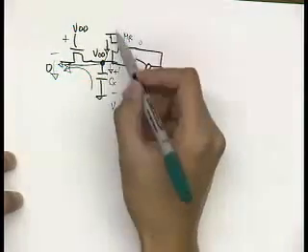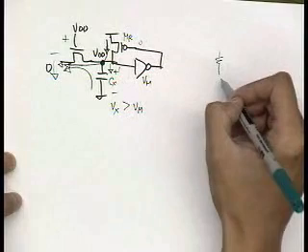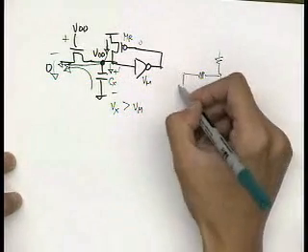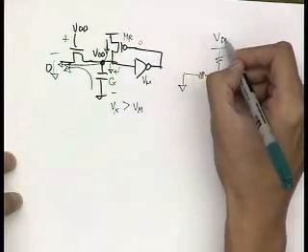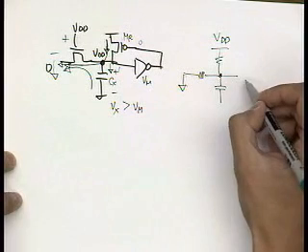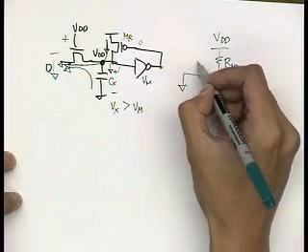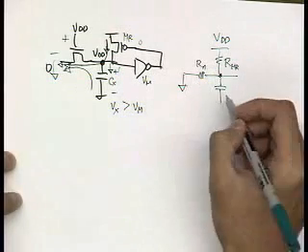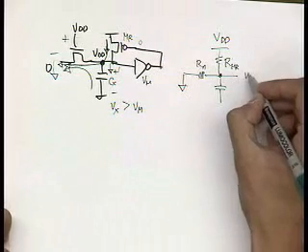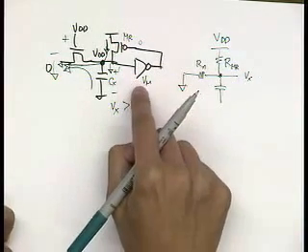Okay, why? You can look at this as what? They're switches, right? So there are 2 resistors and a cap. It's VDD. What happens? It depends on now my R of R and R of this N. This could actually get stuck at some voltage, Vx, that won't be able to switch my inverter.